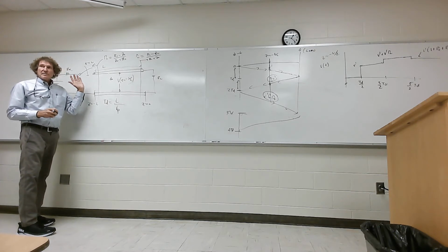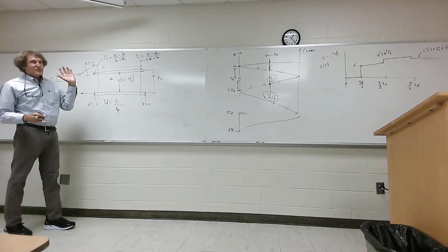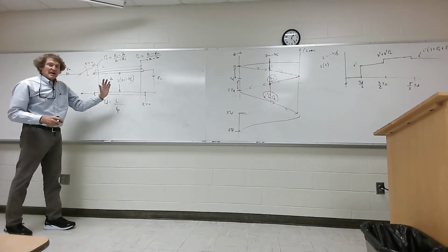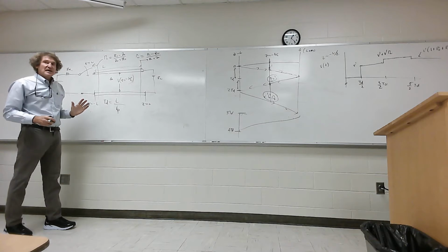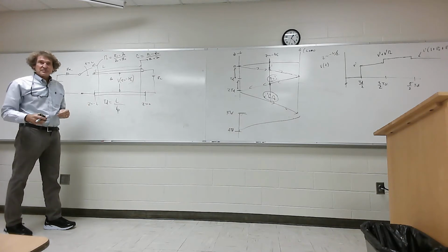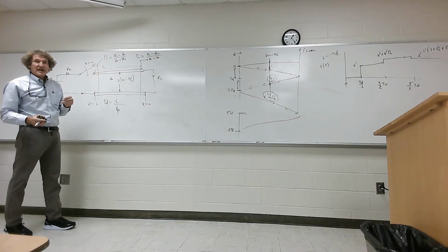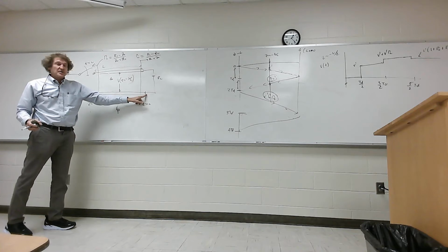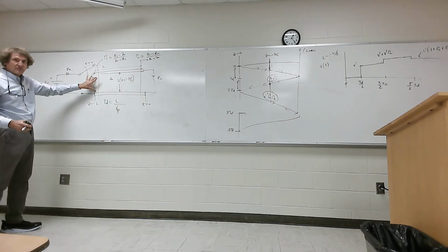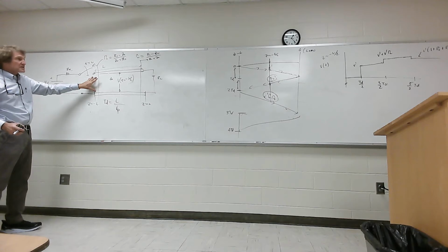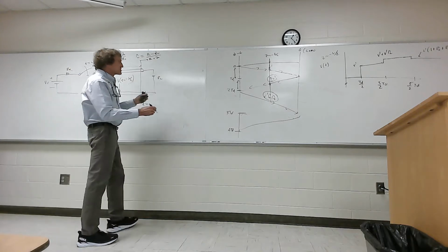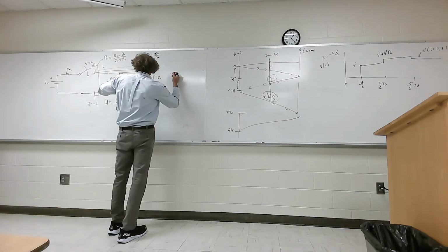Well, in the limit, as time goes on, and I'm being a bit sloppy with how I say this, as this wave bounces back and forth over time, this starts to look less and less like a transmission line and more like two pieces of wire. And in the limit, as t goes to infinity, that transmission line is just too short. It's a short circuit. You can take this and stick it right here. Y'all follow me? You can eliminate the transmission line altogether and just put the load right next to the source. So what would the voltage have to go to on this line?